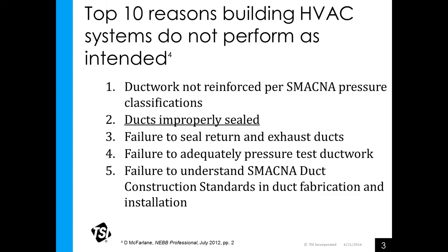Second most important reason I find often is ducts are just not properly sealed. Again, time constraints, working through, trying to get the job done on time, trying to work with limited resources. Even on critical applications, I find ducts very, very improperly sealed more than half the time. Also find that return and exhaust ducts are not sealed properly as well. So you're losing a lot of the dynamic performance of the system by not doing that.